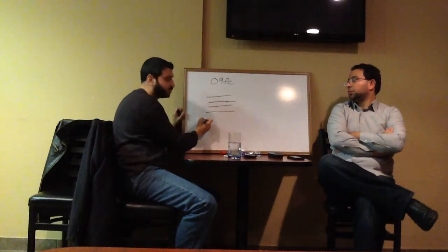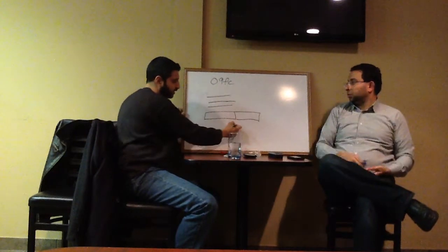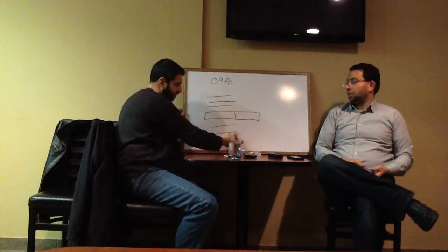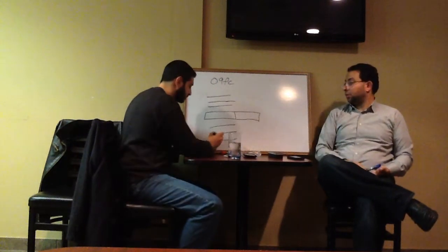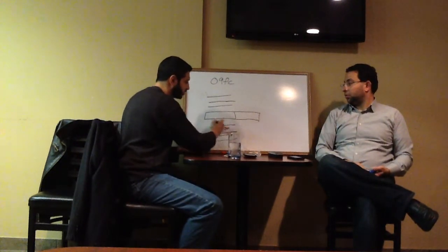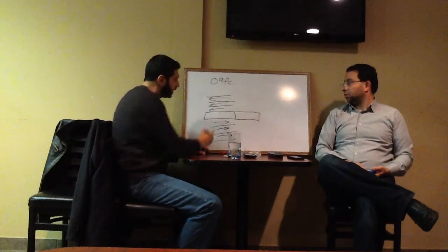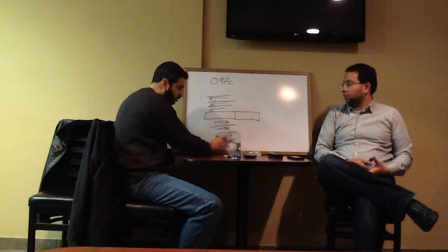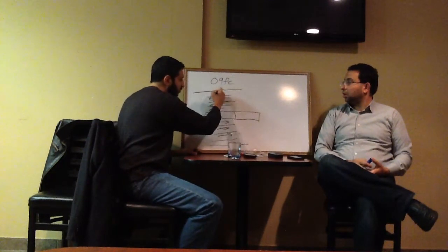Then you're going to have your median in the highway most of the time, a concrete barrier, and then the other three lanes. This is one way, the other way is the other side. Then on the outside you have your shoulders, another 12 or 15 feet.